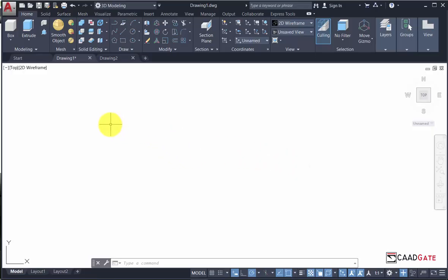So to get started now, let's say we want to create a 1-inch angle bar. Let's start with something really practical. Drawing a 1-inch angle bar in AutoCAD. So as a general rule, when you want to create something that will be extruded, you want to convert from 2D to 3D, make sure you use a command called polyline to do your drawing.